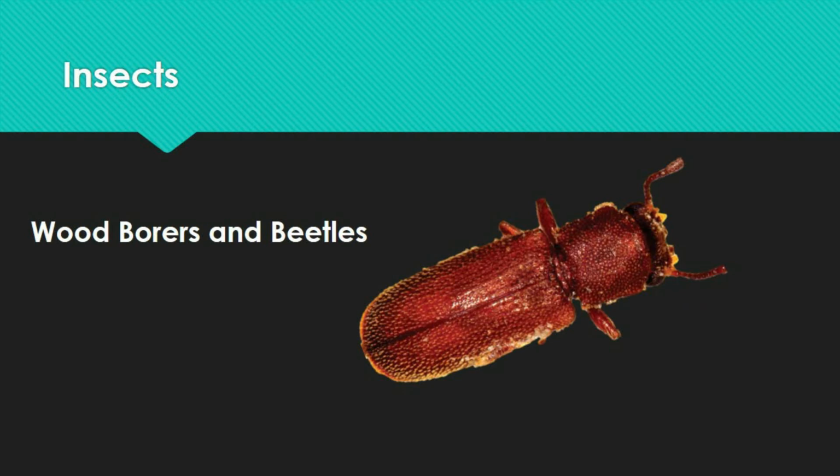Standing poles with interior deterioration are attractive to pillbugs and Pacific powder post beetles as well. They're drawn to moist wood and are most frequently seen near the ground line of the pole. Both species resist direct sunshine and are normally introduced to a pole via seasoning checks. Powder post larvae construct tunnels in the heartwood beside the treated shell, whereas pillbugs make little nests and feed on decaying wood fiber. Prior to pupation and emergence as an adult beetle, these larvae may be found in the wood for up to 20 years. In most circumstances, just a few larvae are present in any individual pole, and pole failure is uncommon due to these bugs. The presence of both of these insects does imply that there is likely substantial interior deterioration, however.